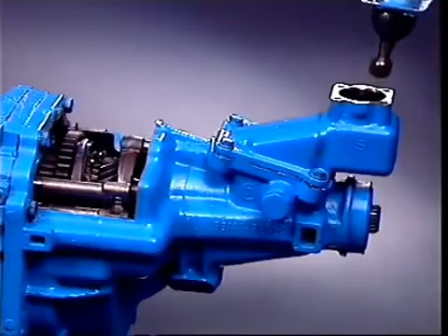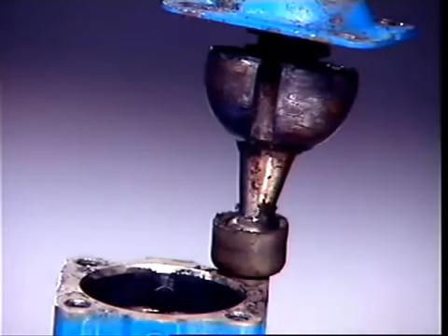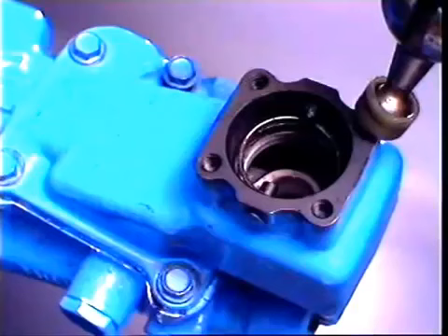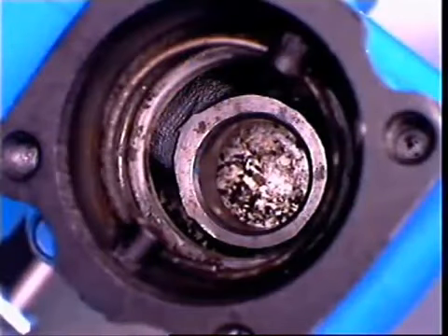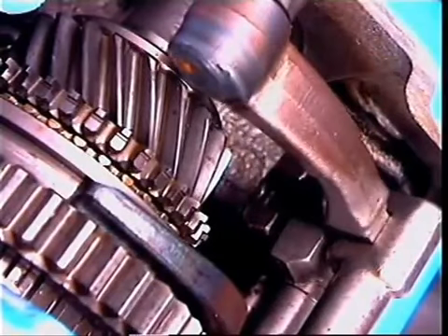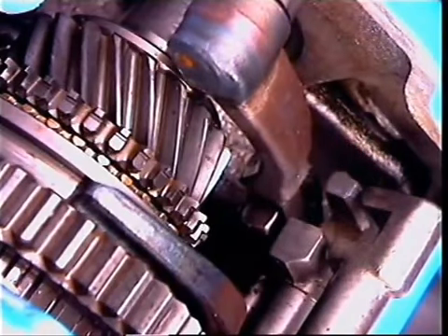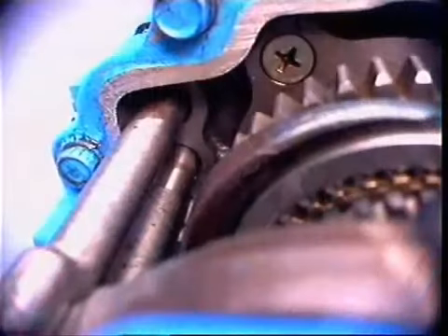It can also be mounted in the top of the gearbox, where it acts through a ball pivot in the top of the extension housing. In this design, the lower end of the gear lever fits into a socket in a control shaft inside the transmission extension housing. A short lever on the other end of the shaft is located in a selector gate, formed by slots in the 3 selector shift rails.